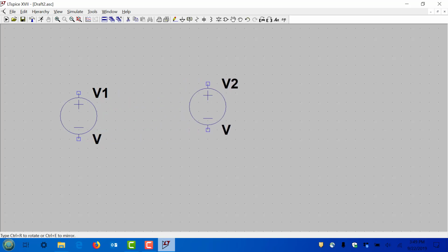When you take your mouse button away, you see that there's another copy of the voltage source in case you want to put another voltage source on your schematic. So if you do, you can keep placing these voltage sources in your schematic, as many as you want. Here we only want to place one voltage source. So we're basically done with placing sources. At this point, you could either hit the escape button on your keyboard, or you could click the right mouse button, and that will exit out of this component entry mode. So it's quite simple. Now we have a voltage source placed on our schematic.